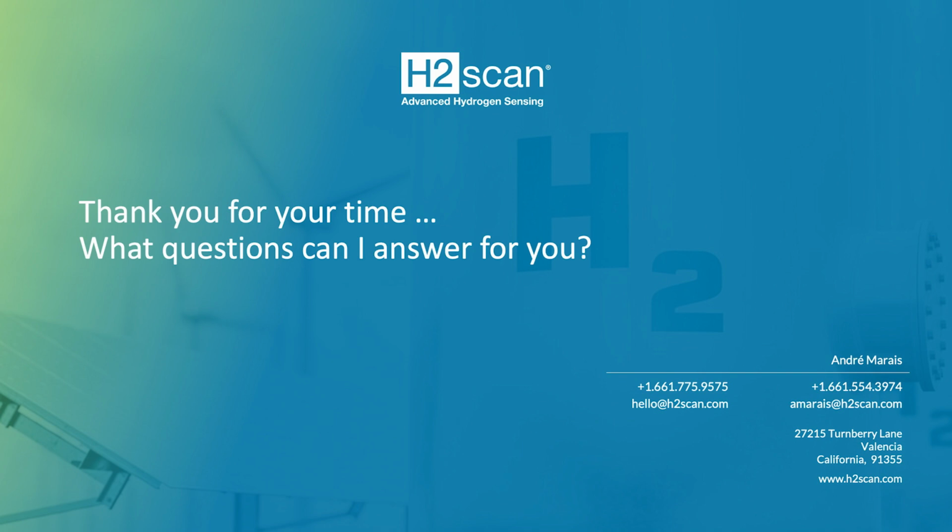First, it's highly mobile. So if you have a free breather transformer, or a transformer with the smallest of leaks, or transformers where hydrogen can find a way through, it will. Hydrogen is particularly mobile. You saw on one example it dropped off and fell to zero. We had to look at it, and it had a breather. My opinion is the breather wasn't operating as well as it should have, and so we saw some hydrogen escape through there.